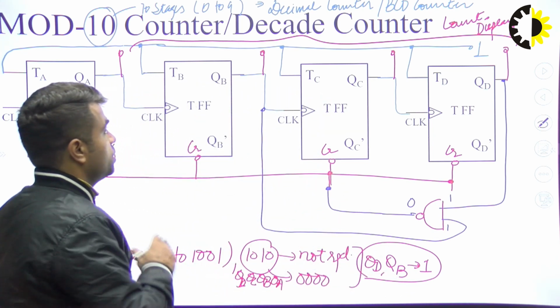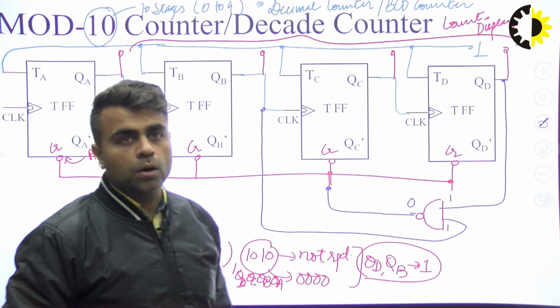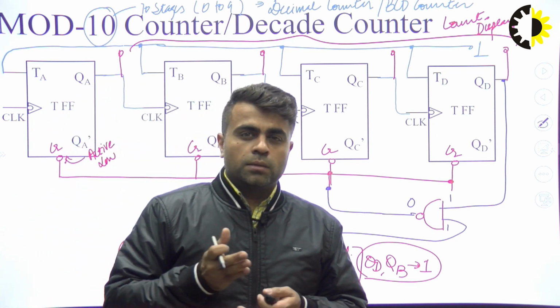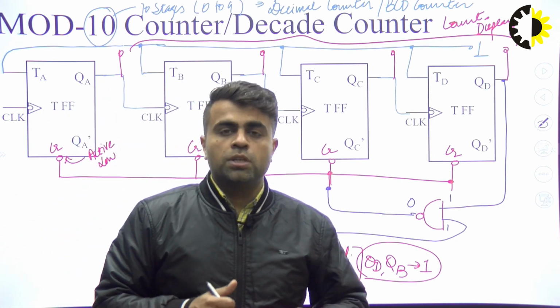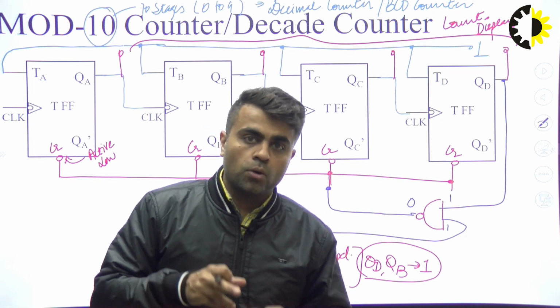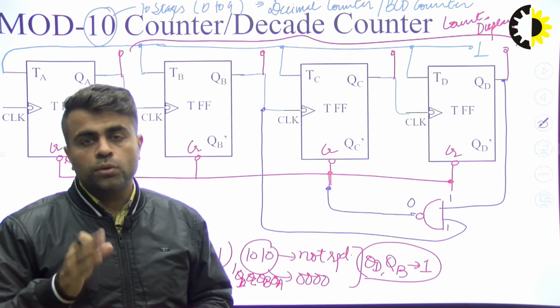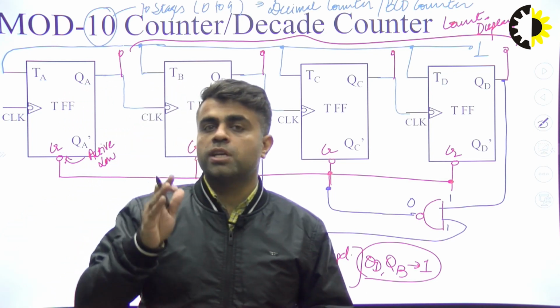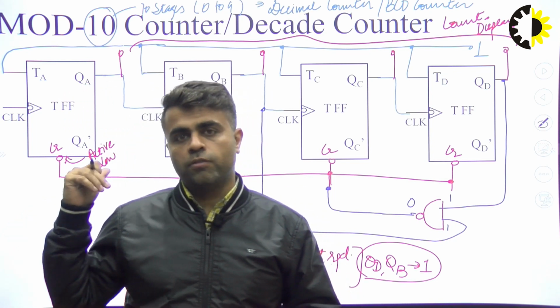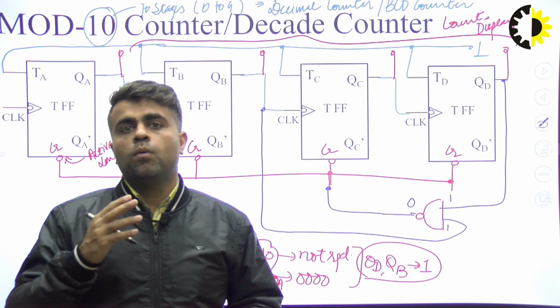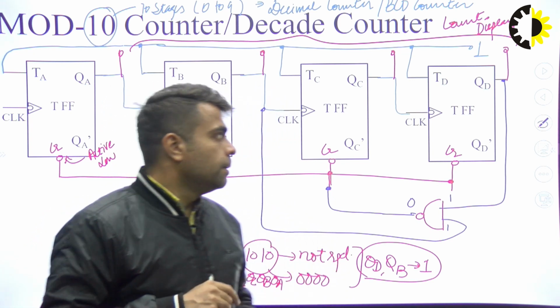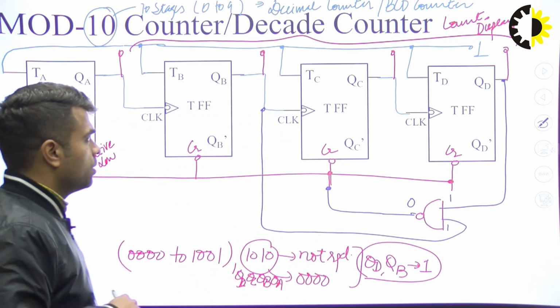So this is how we can design a counter in up mode, down mode, using any clock, and a counter which can count in truncated mode. That means we are not counting up to the full scale value, because for this 4 flip-flop arrangement, the full scale value would have been 1, 1, 1, 1, which is 15. Okay, so this is about the counters.